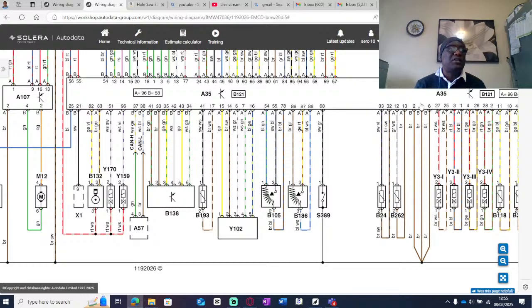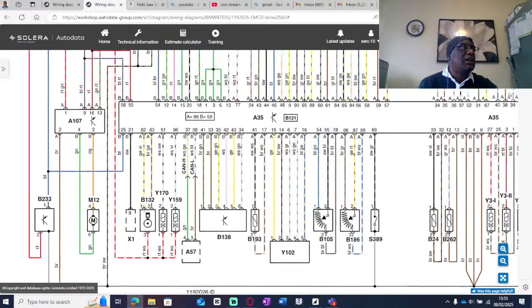If you disconnect the ECU and come to 2B, 4B, 6B, you will get ground. If you don't get ground, you have an open, then you're in trouble. You need to get that one sorted. Follow that ground, follow that open, and get it sorted. I showed you how to check opens last stream.